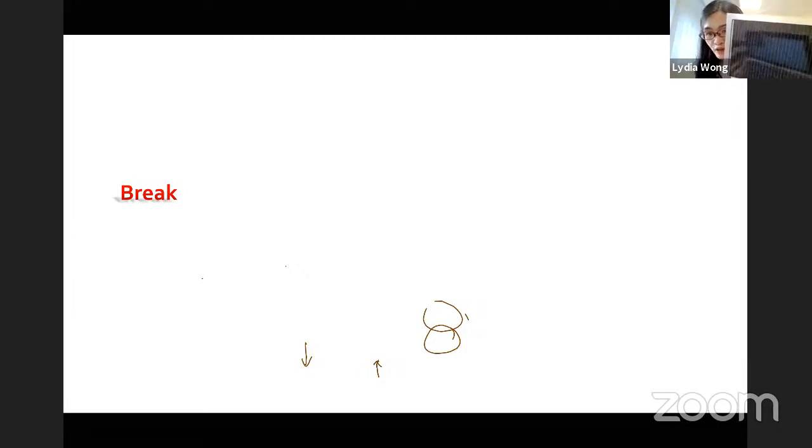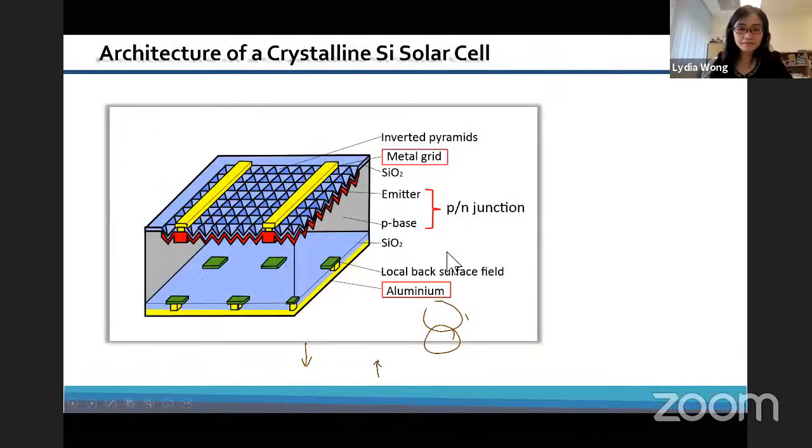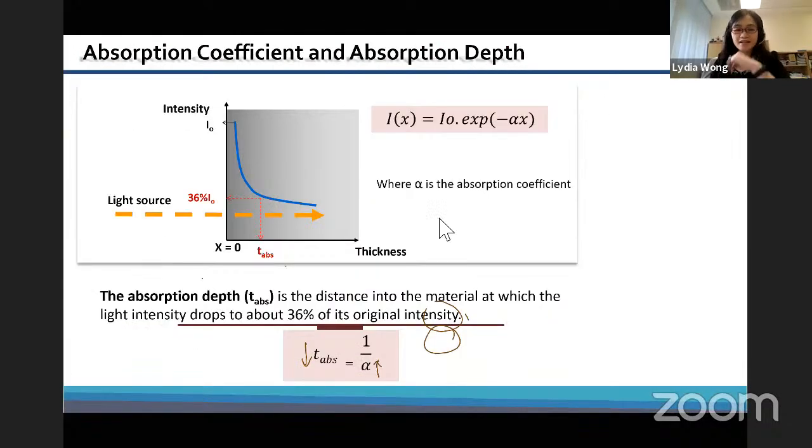However, there is a negative effect to this. When you have less electrode, you collect less electrons. So your power conversion efficiency actually drops. So there is a trade-off. So how people circumvent this problem is they dig inside the silicon, make a buried junction. So maybe let me see whether I have the picture here. Yes. Can you see my screen?